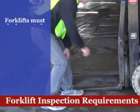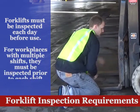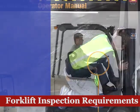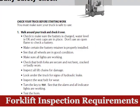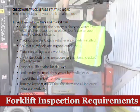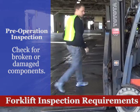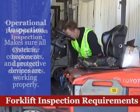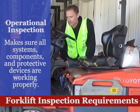Forklifts must be inspected each day, prior to operation. If your company works in shifts, the forklift must be inspected prior to use on each shift. The operator's manual will list the required inspection items. You should use a checklist, so that you don't miss important areas. The inspection consists of two parts. First, a pre-operation inspection must be made, to verify there are no broken, or damaged components. After this walk-around inspection is completed, the driver must perform operational checks, to verify that the vehicle is operating correctly.